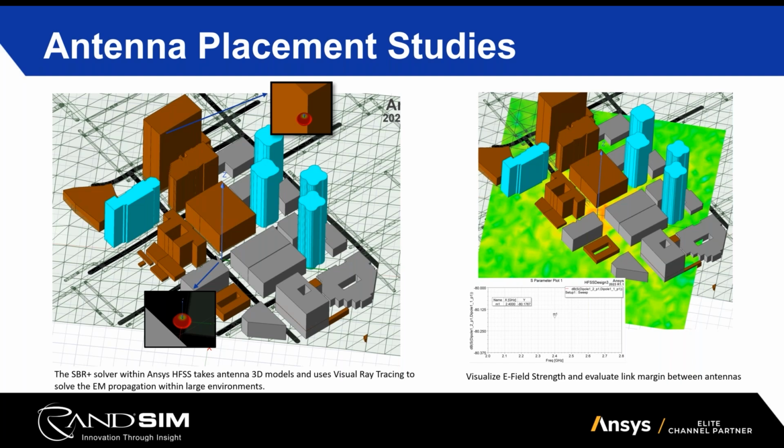of the street. And what will happen is it will leverage visual ray tracing to propagate rays that bounce through this environment. This is a to-scale environment, and we have applied boundary conditions to the different structures and buildings that represent those specific materials. So we can calculate, if it's hitting glass, some will reflect, some will transmit. If it hits solid concrete, most of that's going to reflect off, but it will have some attenuation accounted for it.